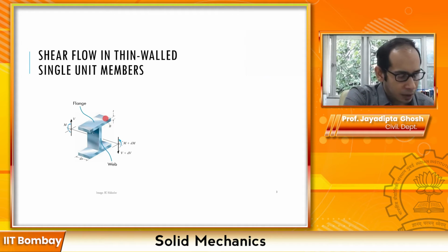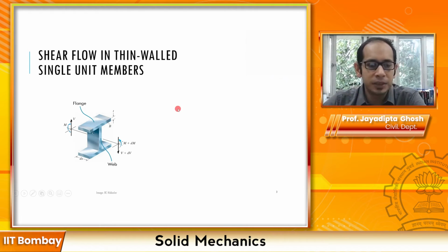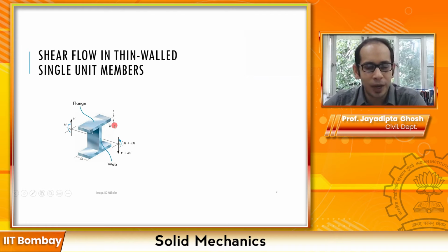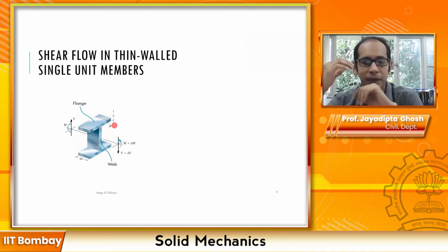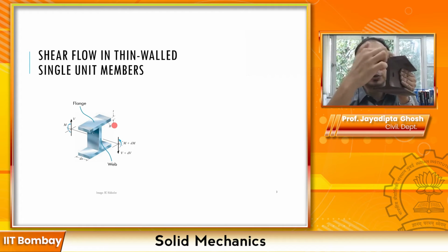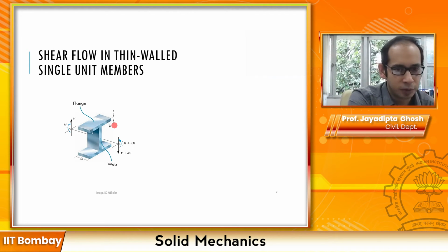Now, one very important thing, you see, this beam is subjected to this M and M plus dM over here. Because of this moment, you are going to have those normal stresses. Remember, sigma equals My by I. Now where are these stresses maximum? It is always maximum at the top and the bottom. So if I am having a moment, the normal stresses are going to be highest over here as well as over here, maybe tension or compression depending upon the nature of the moment.